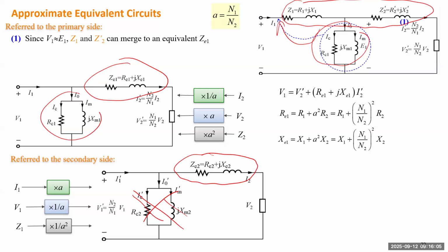This structure is very similar to the structure of any source, like a generator, right? In the generator, on the source side we have an EMF, an excitation voltage, connected to a synchronous reactance and also the armature resistance, which then powers the load of the external system. So now we have generated a structure very similar to the equivalent generator circuit.